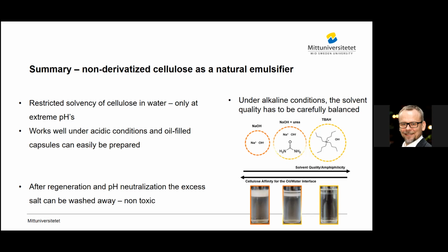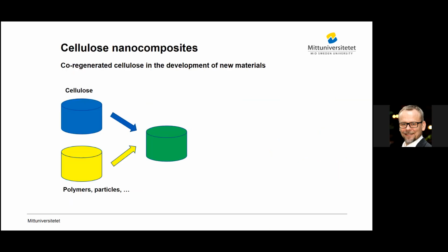Okay, then I thought we move on, still going into cellulose, but into the more composite world and the different kinds of composites that you can make if you utilize, for instance, these water-based solvents. It might be possible in other ways, but we have studied cellulose dissolution in water-based solvents, and usually we use either lithium hydroxide and urea to dissolve it, or sometimes sodium hydroxide and urea.